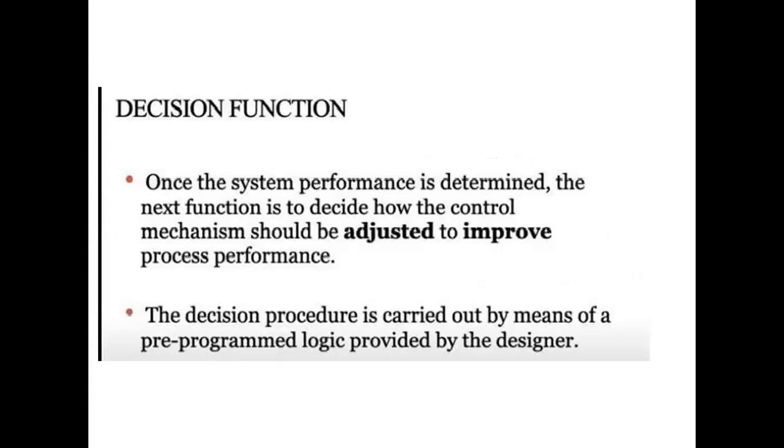For example, you want to have maximum production rate. That is one aspect to look at. So the logic could be based out of that particular strategy, or it could be because of machining cost. Or it could be because you want to have the quality, precision and accuracy much required. So based out of these pre-programmed logics provided by the designer, the decision procedure is carried out.